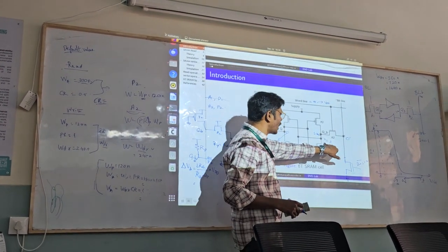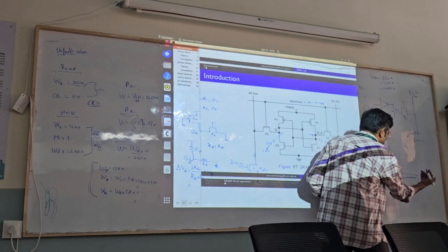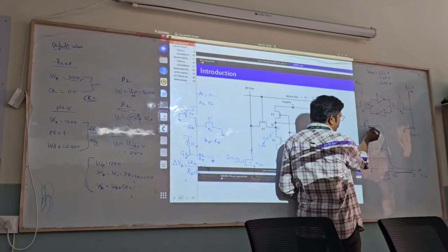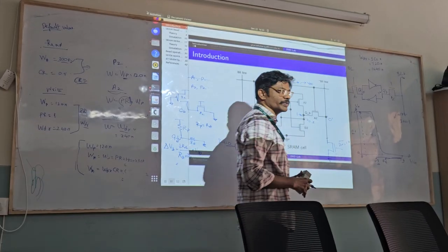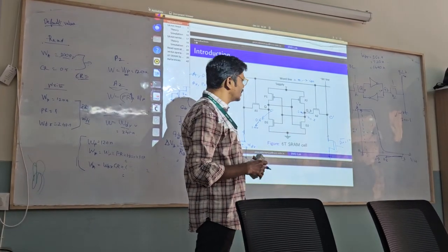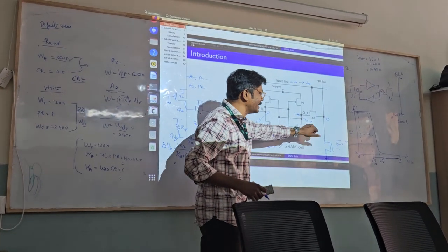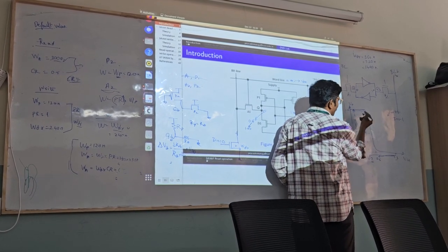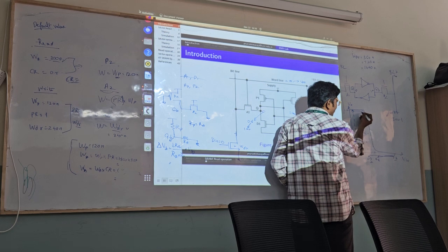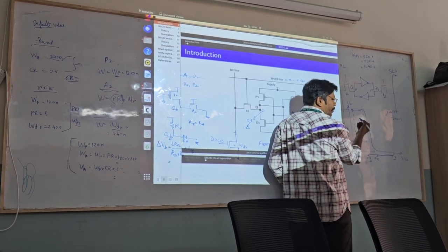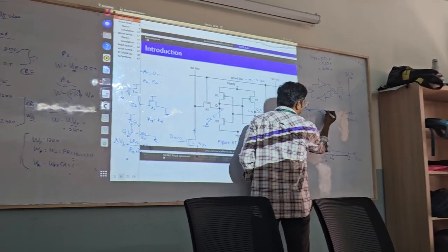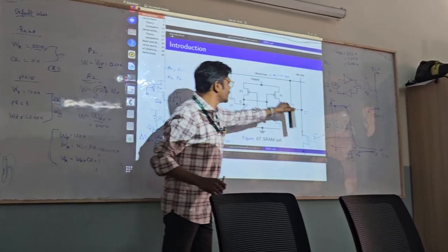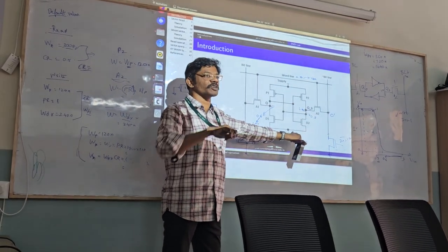Clear? So when I'm able to switch from 1.2 to 0.3, then I am in a safer zone so that I can pull this all the way to 1.2. Okay? To be frank, while I'm performing this 0.3, the exact voltage, when you perform a VTC graph, will not be exactly equal to 1.2, but rather a value close to 1.2, which means the value I might have would be around 1 volt. But you know, it's a regenerative feedback circuit. It's a positive feedback circuit.